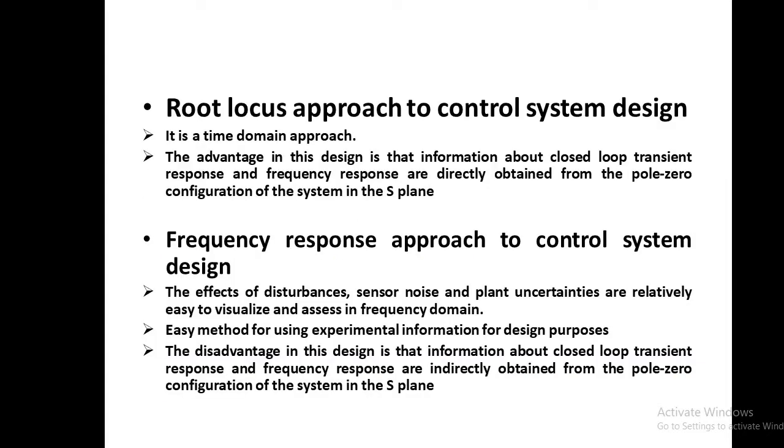And these compensators may be designed using two approaches, that is root locus approach and frequency domain approach. In frequency response approach we are using Bode plot, Nyquist plot, Nichols plot etc. The root locus approach is a time domain approach, and the advantage in this design is that information about the closed loop transient response and frequency responses are directly obtained from the pole zero configuration of the system in the S-plane.